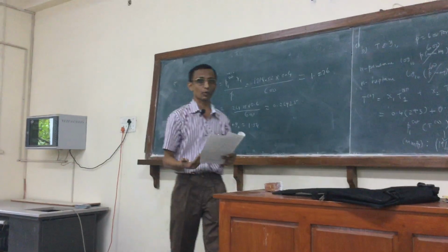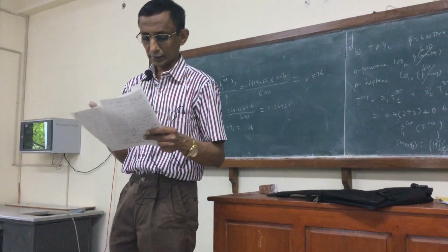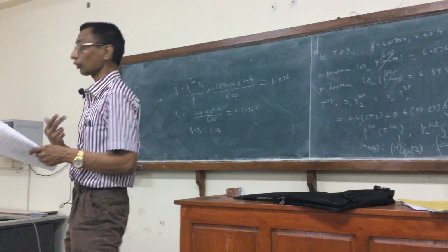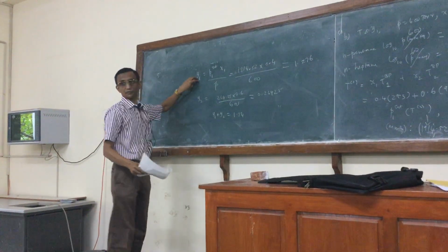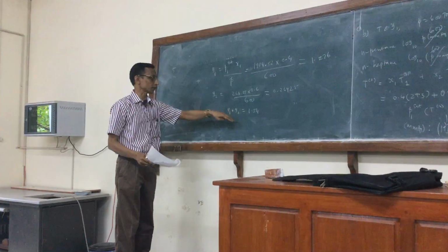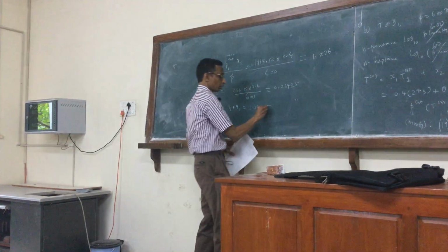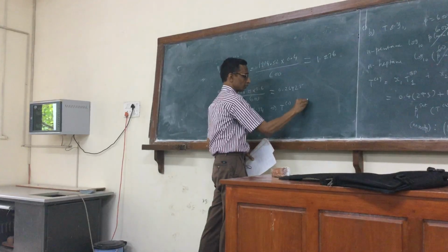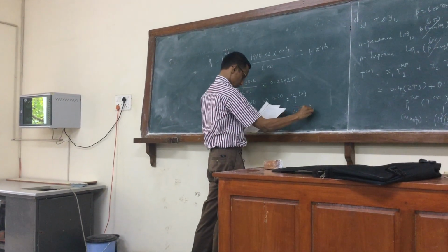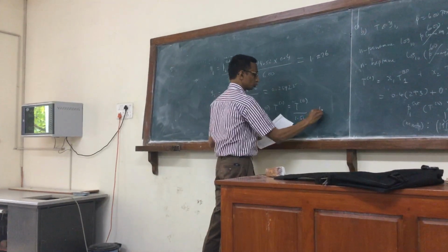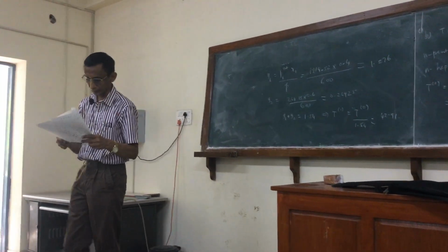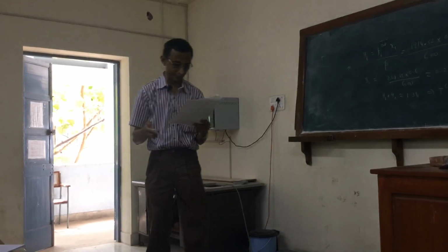And so now the question is whether we should increase or decrease the temperature. Clearly we should decrease the temperature. That's what we saw, because if the y's are becoming greater than 1, it means I have chosen a higher temperature, so I need to decrease it. So I can use this itself, and the algorithm accordingly becomes T0 divided by 1.54. So that turns out to be 42.91. So now I am calculating T1 sat and T2 sat at 42.91 degrees centigrade.